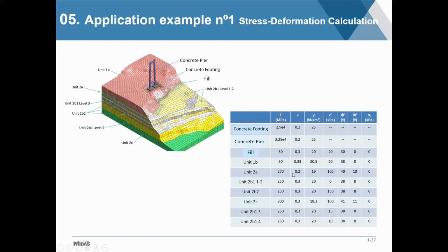Just to clarify, the export process of the mesh does not bring information about the materials. As we will see in this example, once the mesh has been brought into Flac, the user in Flac has to additionally assign the material values to each of the zones.